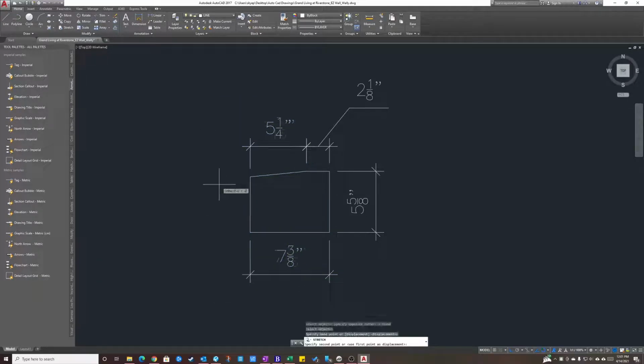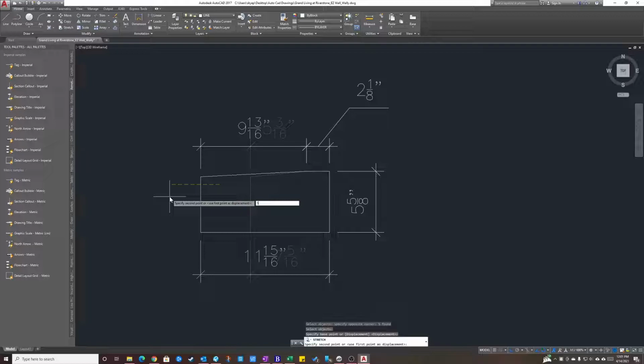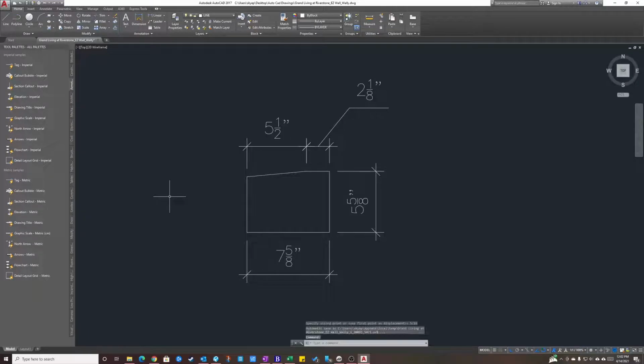So we select it, we right click to activate, we drag it in the direction that we want to stretch, and then we type in our dimension, which is 5/16 of an inch. You can type this in like this, 5/16, because it's already in smaller dimensional terms. But typically if it was larger, I would say do it in inches or decimals because it's easier. But because it's already small, 5/16, you can type it that way. Now you type your dimension and you hit enter.